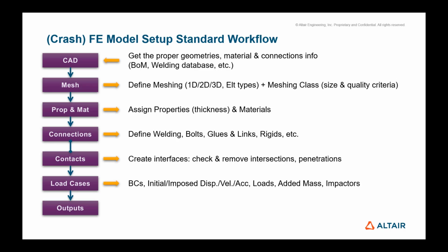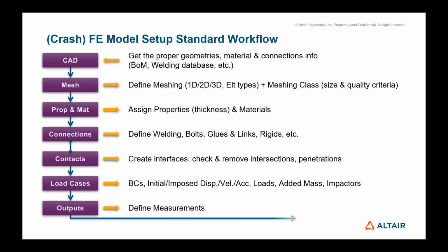Now we must think about output definition. What results do we need? How are we going to measure them? Are there specific nodes for which displacement should be monitored or connections for which forces should be controlled? We are almost ready to run our model.